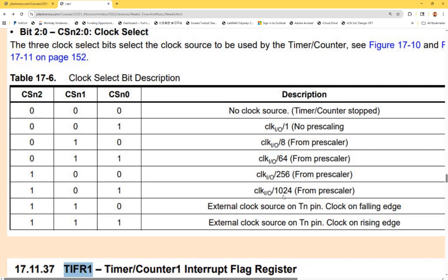So why do we need to slow it down? For playing music, it's still useful to play it at a high frequency, but sometimes think about that. If we want to have a timer for like 1 second, you can overflow the 16-bit count register easily and quickly. So by slowing it down, you can have a longer duration of the timing. You want to count it slower, okay?